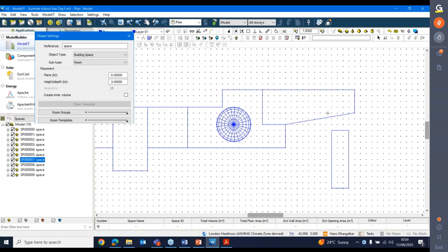So the A and B commands, dx equals A comma B, A and B are the movements in the screen X followed by the screen Y, and it's screen X and Y, not model X and Y. So you can use this dx command in any view that you wish, and the A and the B numbers are movements in the screen X and screen Y, depending on which view you're in.